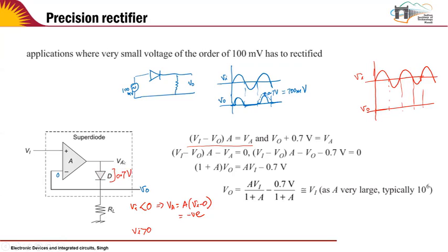So when Va is a positive number, let's say it's 10 volts, then the diode will take 0.7 volts to turn on, and the moment the diode is on, the rest of the voltage will drop here. So if Va is equal to 10, then this will be 9.3, right? And that's what the output will see. There will be a current flowing, 9.3 volts divided by RL would be the I. So that much current will flow into this path.